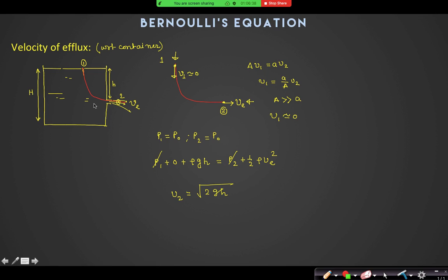So please repeat. We have done a calculation on venturimeter. The velocity was a function of a1 and a2. Yes, sir. So if a1 and a2 are not the same, if small a is not negligible compared to capital A, you will find a similar formula to the one we got here. You can try that, no problem. You will only solve it by this calculation, one second, continuity and Bernoulli.